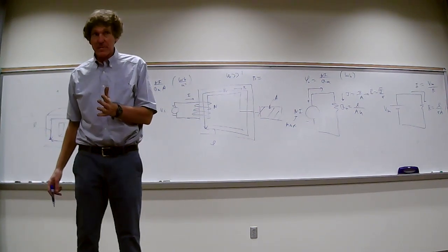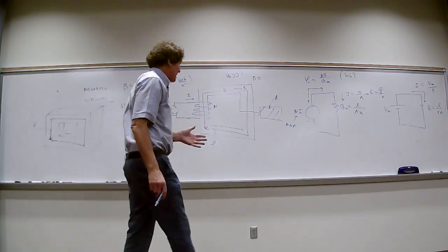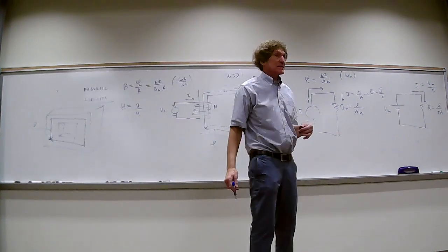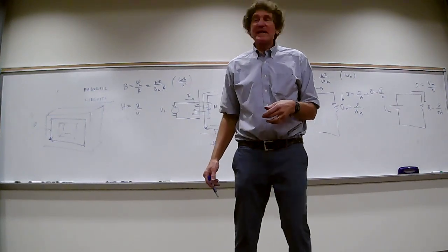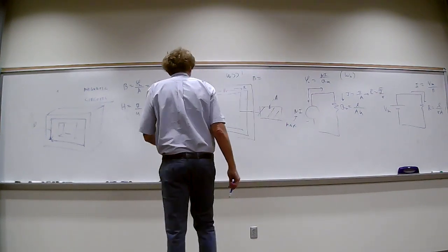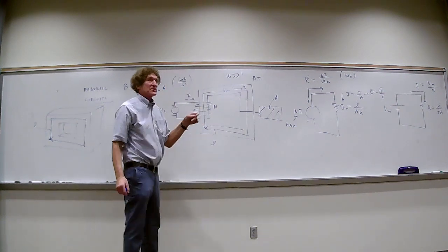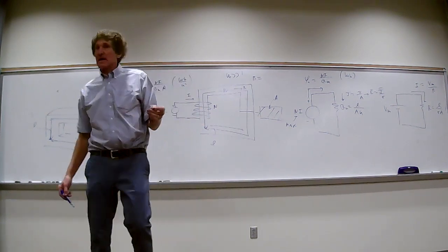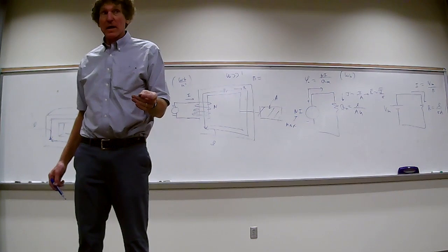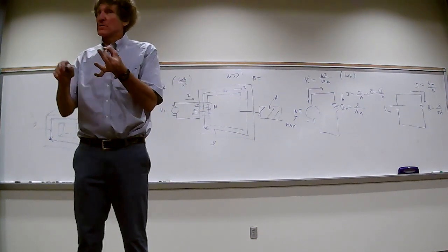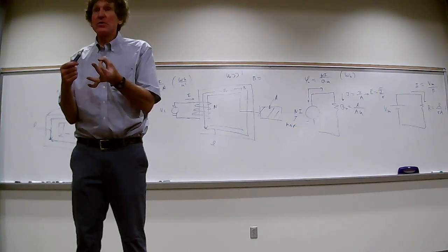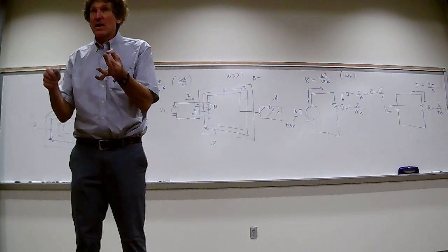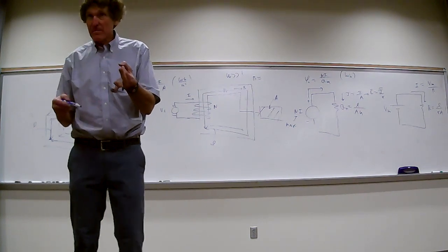Y'all with me? Now finally, after that, if I wanted the inductance, I'm going to throw this out here. Who can tell me how you would get the inductance of this system? What is inductance in terms of flux? It's what? The flux flowing through a single turn, do you all remember that? Divided by the current causing it. But if you had more than one turn, you would have to multiply by the number of turns. Do y'all follow me?